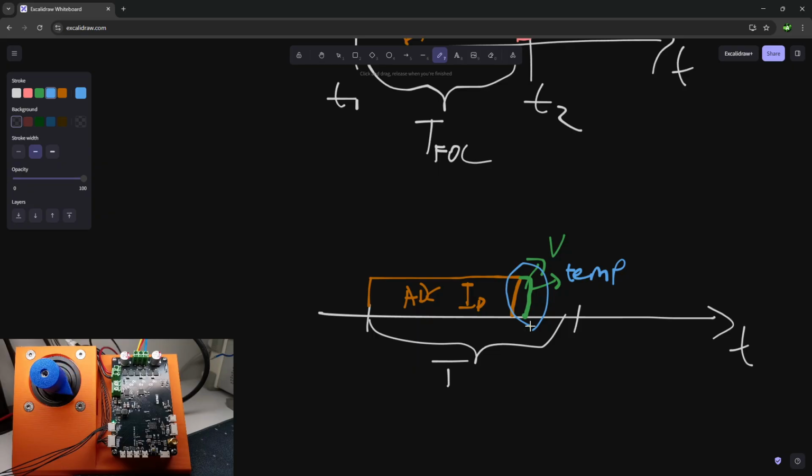And that's fine, I guess, for now. But with a new microcontroller, it can be moved to a different ADC, which will measure them not 20k times per second, but I'd say 100 times per second will be more than enough. And for temperature, it can be even lower, but given that it will most likely be the same ADC, it might as well be together.